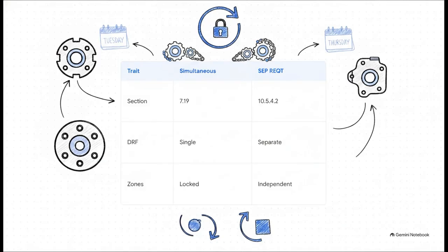Here's the root of that assembly nightmare. It all comes down to how the ASME standard treats multiple patterns by default. If your inner bolt ring and your outer bolt ring reference the exact same datums in the exact same order of precedence, the standard automatically clumps them together into a simultaneous requirement. That means the inner and outer patterns are treated as one single, locked together super pattern. Their tolerance zones cannot translate or rotate independently.